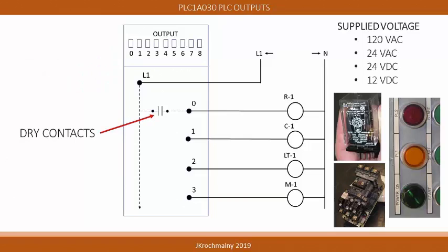This power is often 120 volts AC and controls relays, contactors, light bulbs, and more. It is these devices that operate motors, lighting systems, electric resistance heaters, and more digital devices. Other voltages could be used here as well. For example, if photovoltaics are being used, perhaps 12 volts DC may be the supplied power source. A system designer could also use 24 volts DC or 24 volts AC power, depending upon customer requirements.